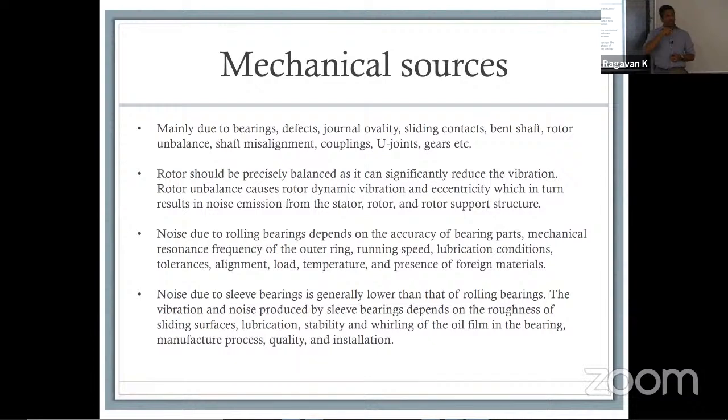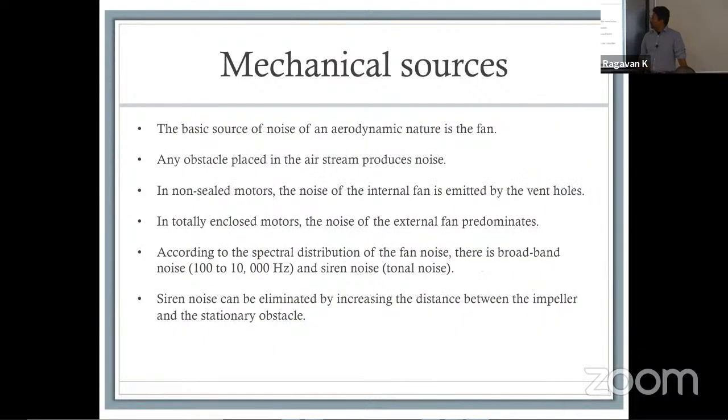When we talk about permanent magnet machines, I will talk to you about that tomorrow. I'll talk to you a little bit about one of the methods we implemented using search coils. And you will see the idea was to identify the fault or the failure as it is happening, instead of waiting until the sensor is gone, until the system is actually in jeopardy. You can also have noise due to rolling bearings, and sleeve bearings have a different kind of noise. These noises are identified by the type of frequency and the intensity of the sound that they produce.